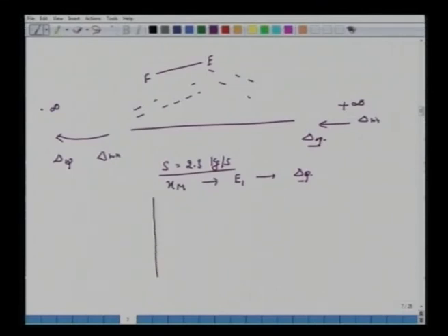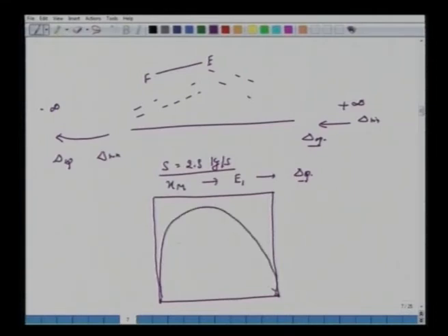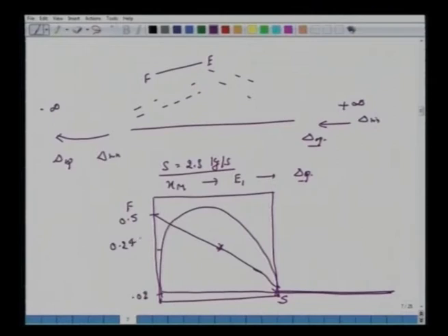What we did, since the amount of solvent was given to us, we connected F with S. We got this xm, 0.246, and then when you connect this RNP with this, or XNP with this, you have E1. So now if you extend the difference points, you get your operating del, then start making the tie lines, say E1. Here the tie lines were downward, so you get R1. First stage, connect with this del.